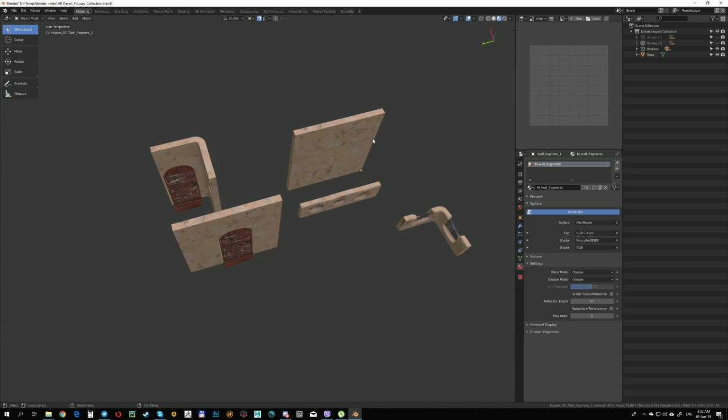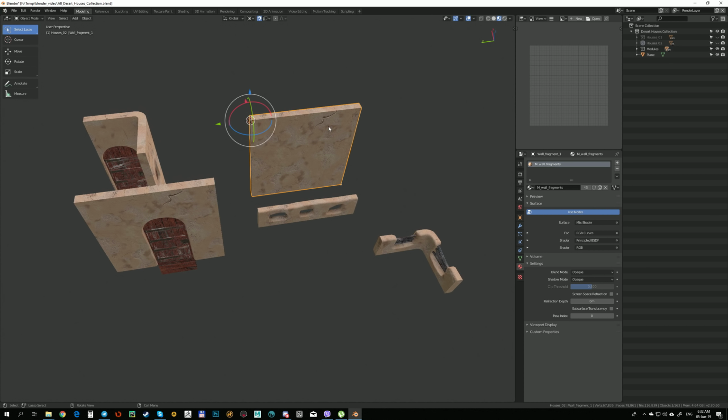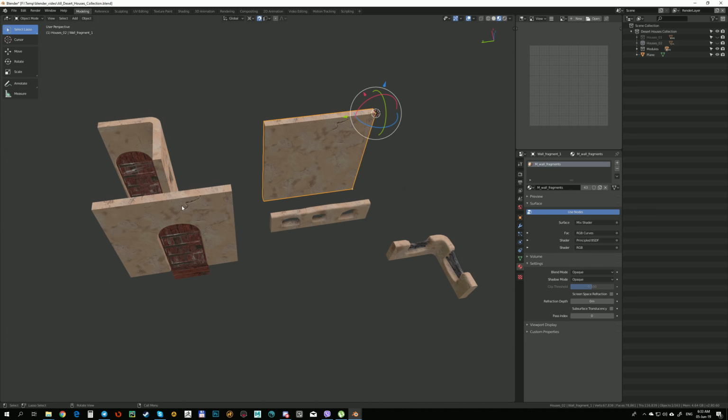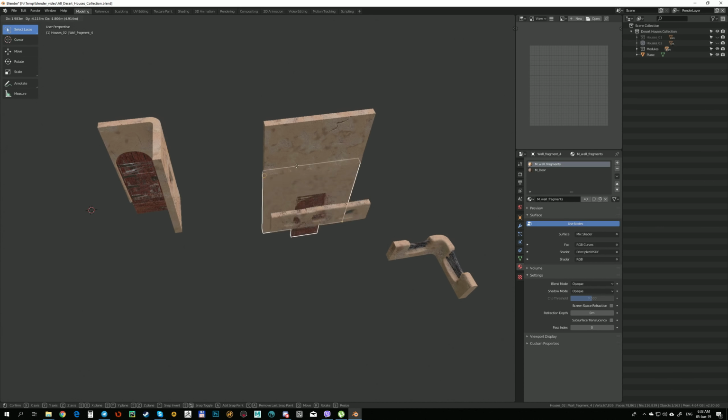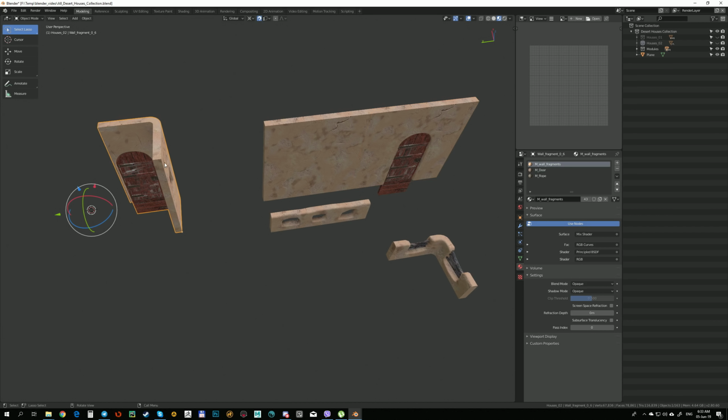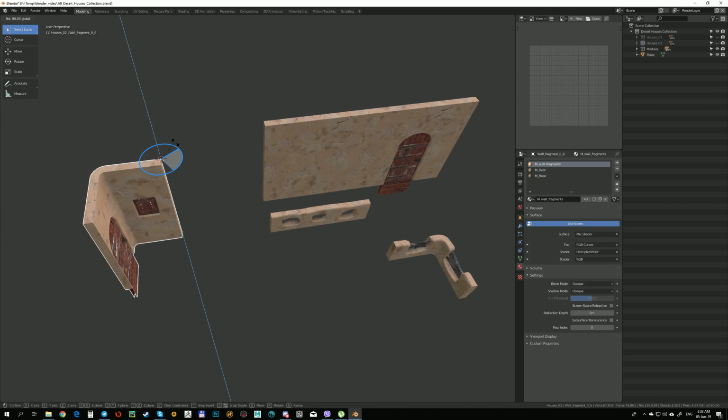Now if I hold Shift and right click, I can set my pivot point. I can make it visible using this option. I can set my pivot point to whichever vertex I like because snapping is on, and my 3D gizmo will follow the 3D cursor. With this I can easily move and snap together different modules. I can hold Ctrl and rotate, snapping to every 5 degrees.